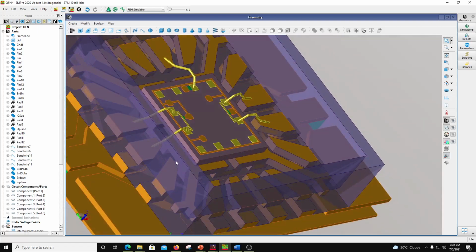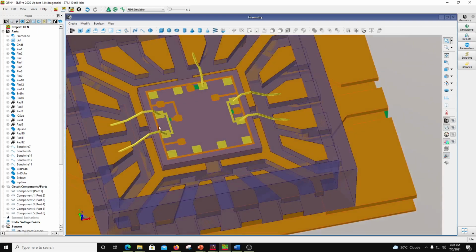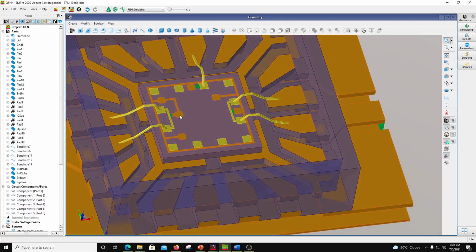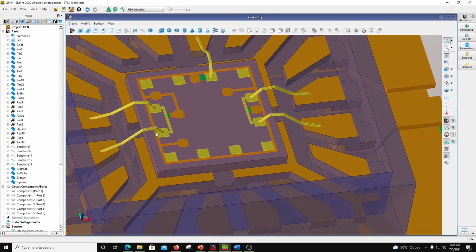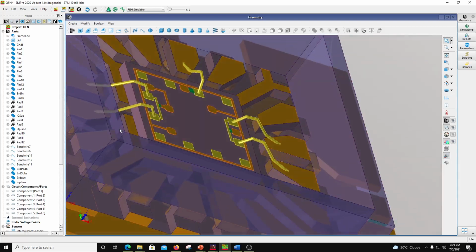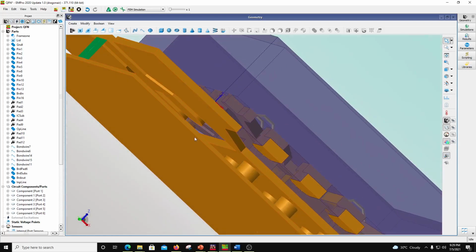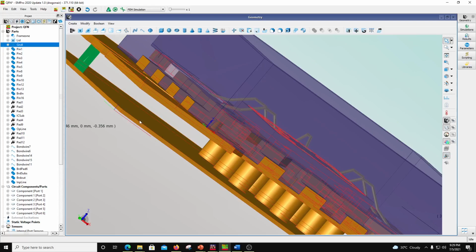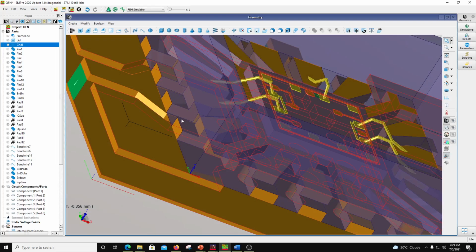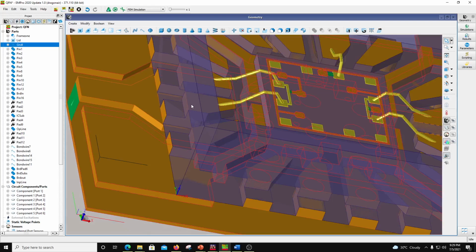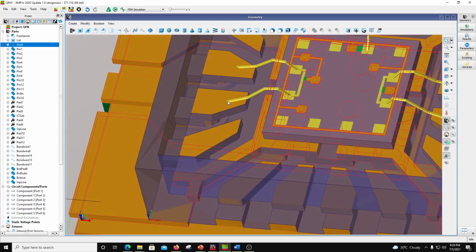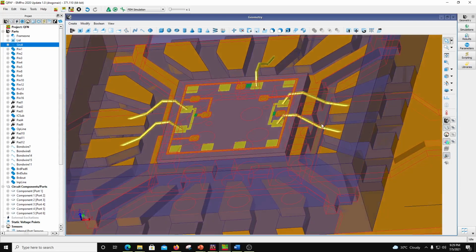So my work starts from these parasitics. So if you see, the bond wires give rise to inductance, and then the pads give rise to capacitance here, and then there are capacitances all along the length of the wire, and then the terminating pad also sees a capacitance with respect to ground underneath. So that's the ground underneath, right? And this output also sees a capacitance. So you have a CLC structure here on the input, and similarly you have a CLC structure on the output.